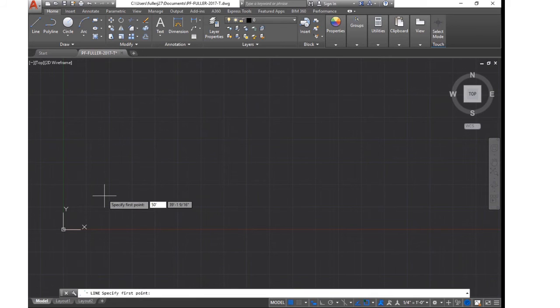Okay. Now I want to get to the next box, because we're talking about XY coordinates here. That first box is 50 feet. That is my X coordinate. Now I want to place my Y coordinate. So I hit the tab button. If you look on your keyboard, on the left-hand side there is a tab button. So I click on the tab button, and it takes me to the next box while saving what I put in the first box.